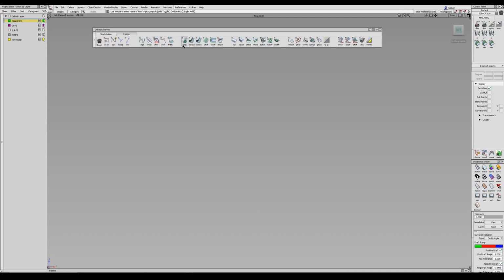The next group is Align. I'm a huge Align fan. And then I have two variations of Extend. This Extend has Merge turned on. And if you have Merge turned on, you only use Extrapolate. Never, ever, ever use Linear. Kind of joking, but it adds multi-knots for Linear, and there's better ways of doing that. So I always recommend if you have Merge on, use Extrapolate. If you need to make something linear, always have Merge off.